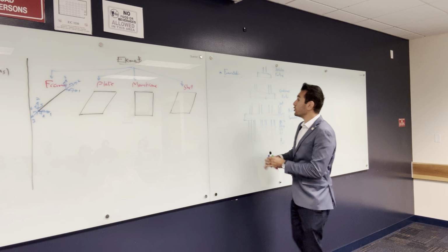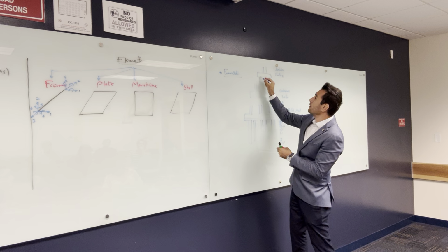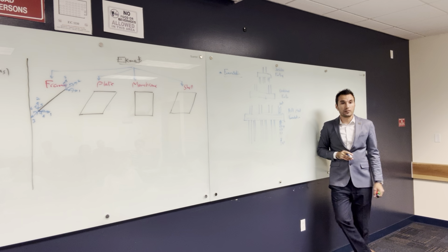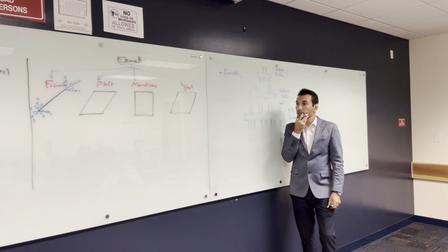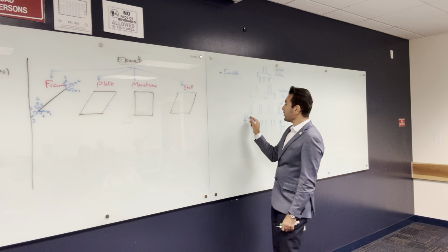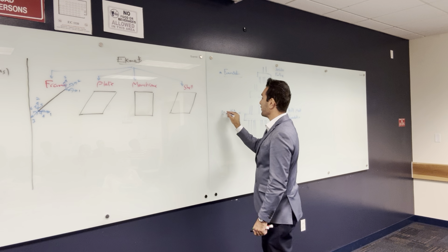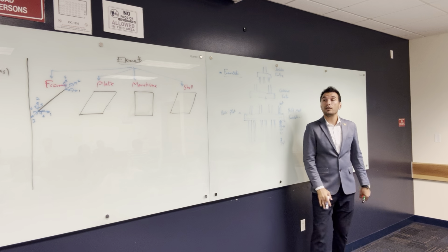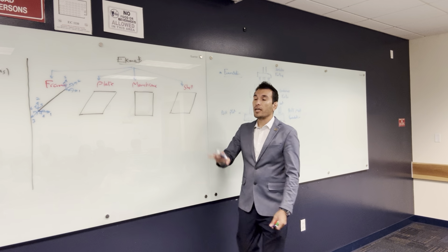And sometimes you don't do the raft foundation and you put piles under it, and that's what we do mostly in bridges. You have one column from the bridge, you put some piles, and you take the load. So yeah, we model the raft as a plate. We call it a thick plate because usually the raft foundation is 1 meter, 2 meters, sometimes 3, sometimes really big. So if you want to use shell, you can use shell as well.